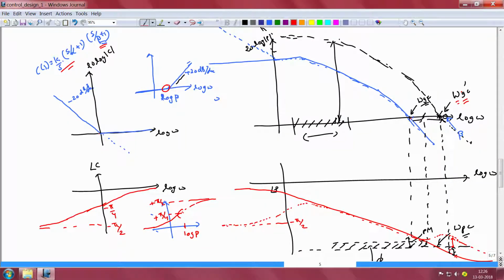If we were to draw the Bode plot of our newly synthesized controller, we see that at omega equal to alpha we will have a 0, and the purpose of this 0, as we discussed in the previous slide, was to improve the mid frequency performance. It was intended to prevent the integrator from attenuating the plant's characteristics and thereby resulting in low gain crossover frequency and sluggish response.